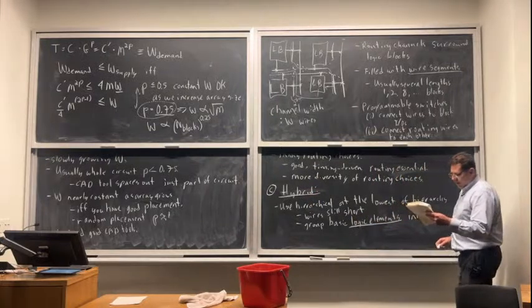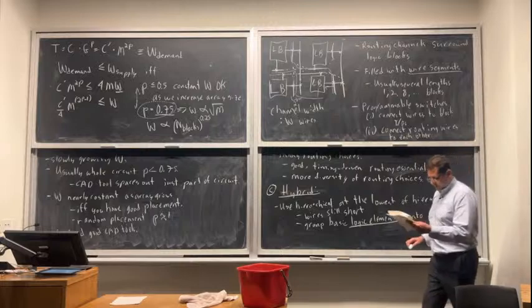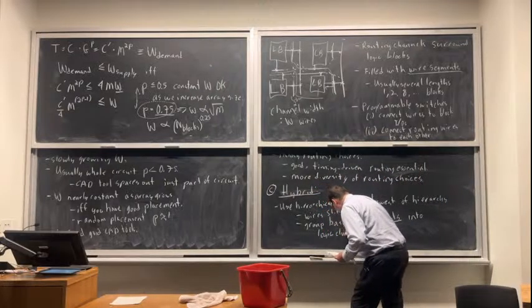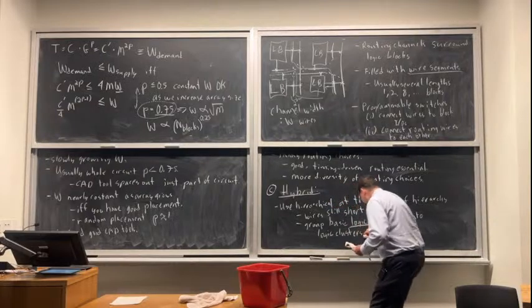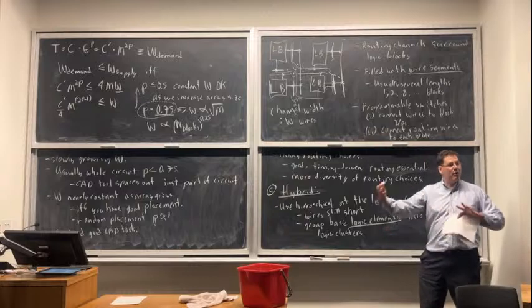It was very small. And then you connected everything together with the island-style routing. So instead, we could take those really small logic elements and group them into what are often called logic clusters. Okay, so they're logic blocks, but they're sometimes called logic clusters to differentiate. They're a bit more complicated.